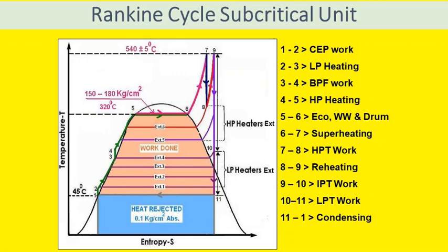From 6 to 7 it represents superheating, and this superheating, as I already mentioned, is taking place in 3 stages. After superheating there is expansion in the HP turbine. 7 to 8 represents expansion in the HP turbine. So post expansion of the steam in the HP turbine, it is again taken for resuperheating or reheating.